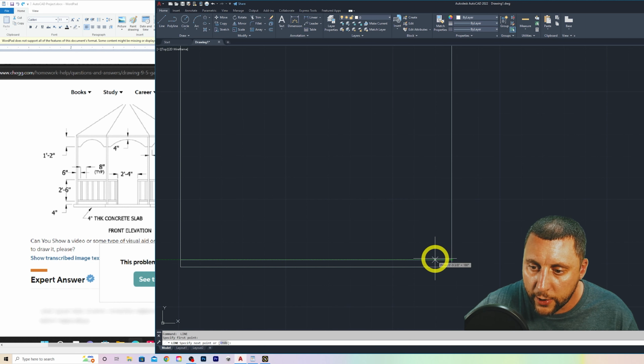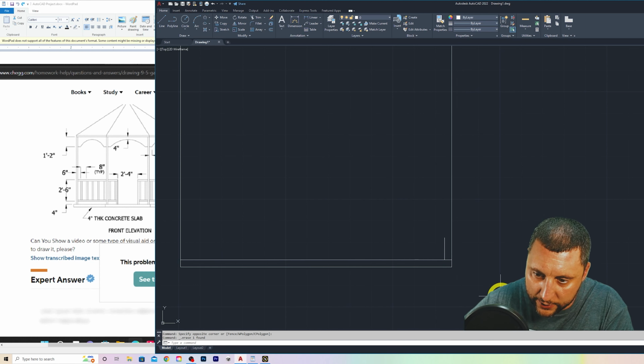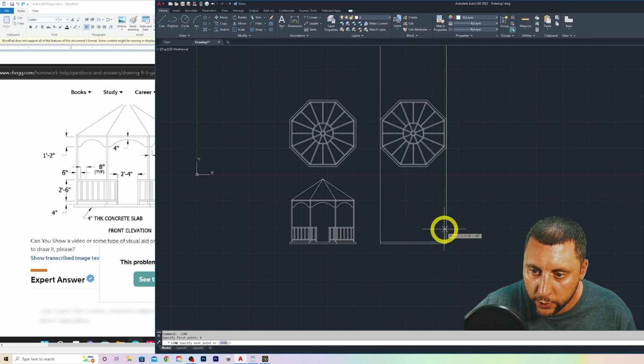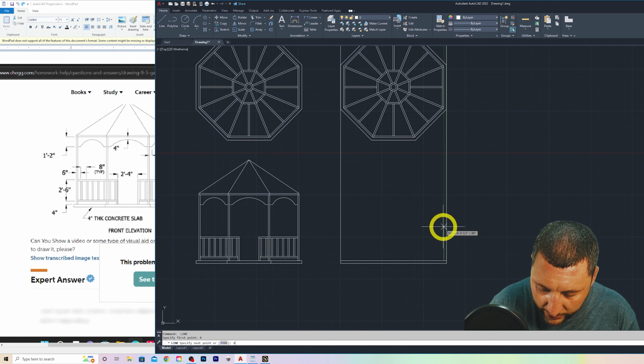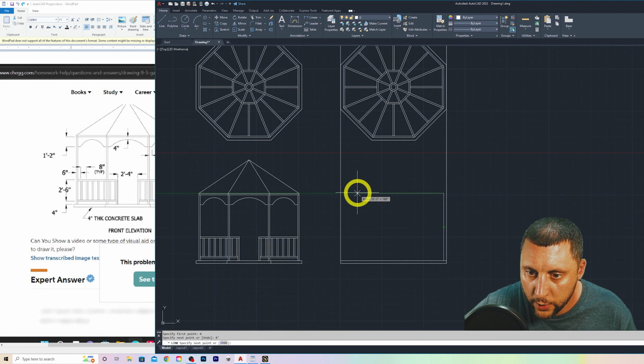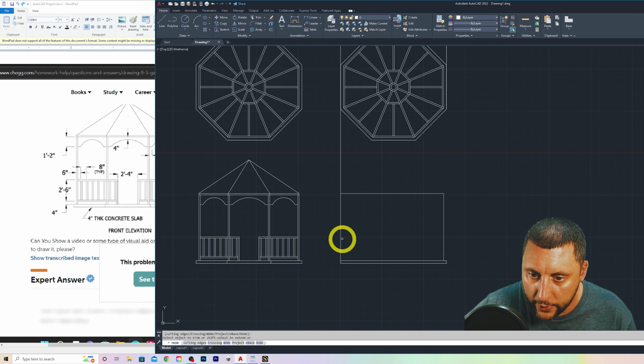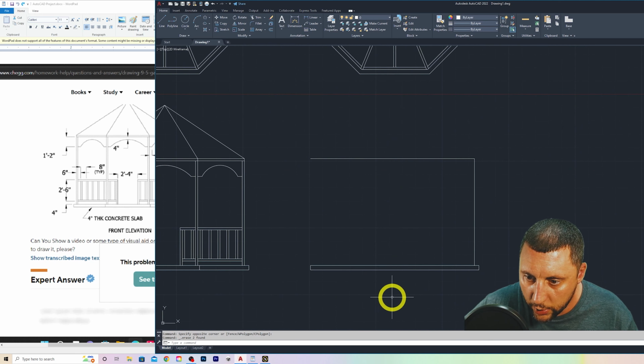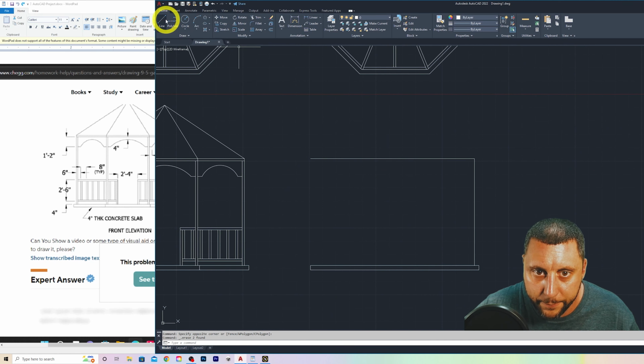Because instead of drawing a line like this, 4, enter, and then going up, now I have to go back and erase that line. It gets kind of tedious after a while when you have to do a lot of extensions. So slide 4, enter. Whoops. Slide 4, enter. You're going to draw up, and this is going to go 8 apostrophe for 8 feet. You come across. I meant to trim that and that. We don't need those. These are left over now.